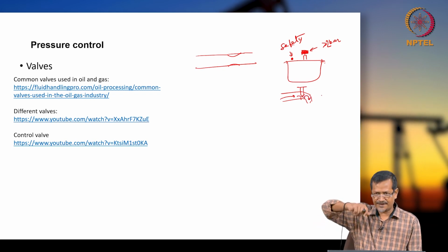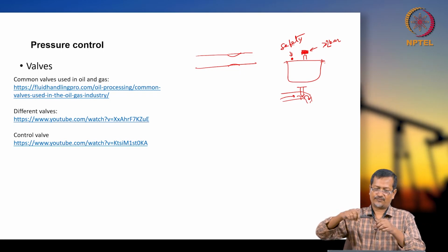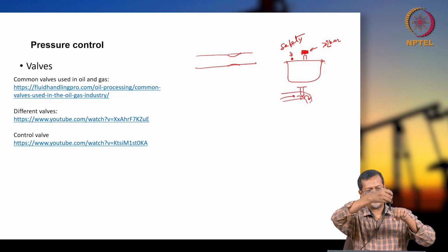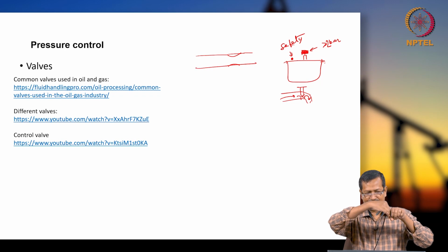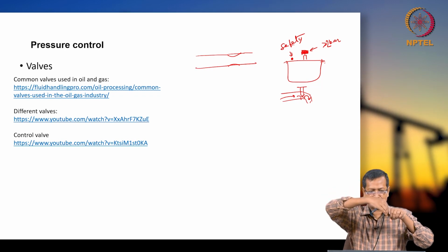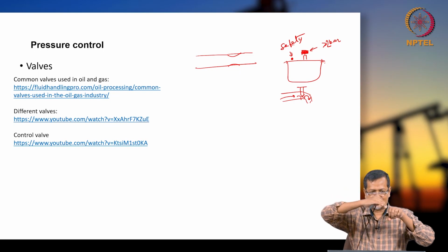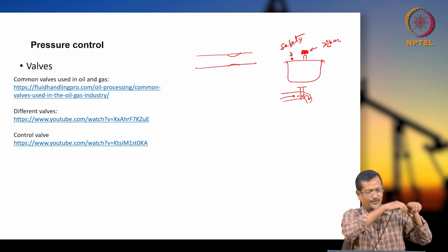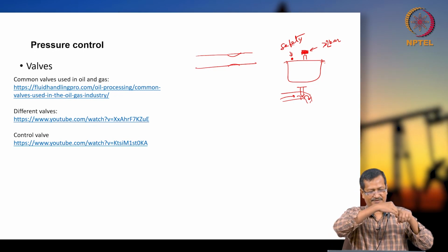If you turn it, let's say fluid is flowing through this small area and you have a pin. When you turn, the pin will close the path. If you turn in the opposite direction, the pin will move up, so the fluid will flow continuously. If you tighten like this, the pin will close this flow path. When the flow path is closed, fluid will not flow. This is the pin type. Okay, so close control is possible.